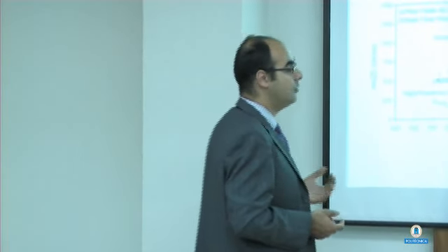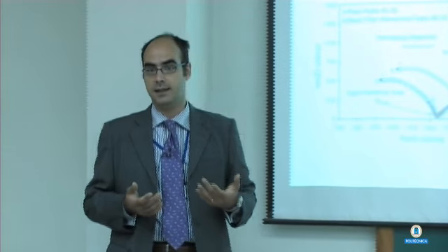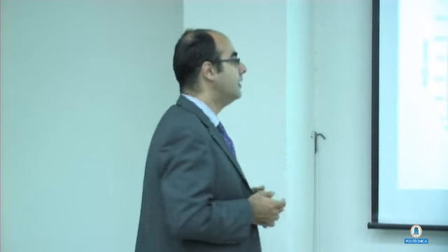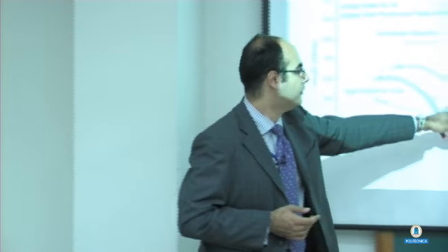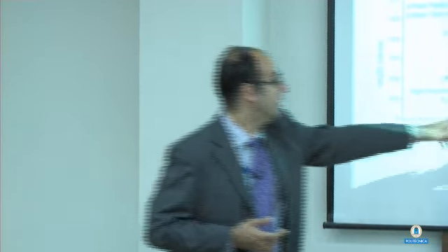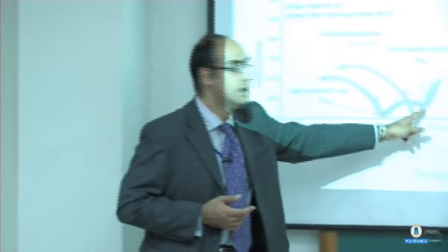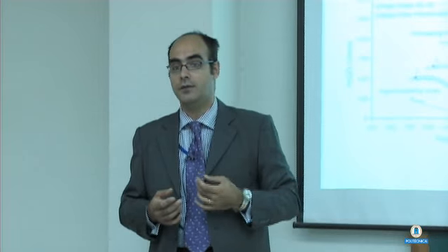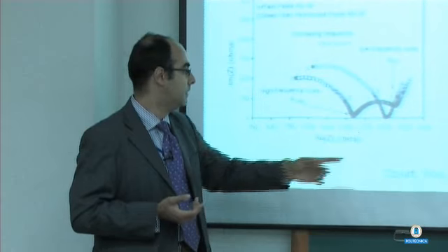When you apply it to a steel fiber reinforced composite, due to a very thin film which forms at the interface between the fibers and the matrix, under the low frequencies of the alternate current, the fibers behave as insulating, so they do not transmit current. And what you measure here, this cusp, is very close to the resistance of the unreinforced matrix.